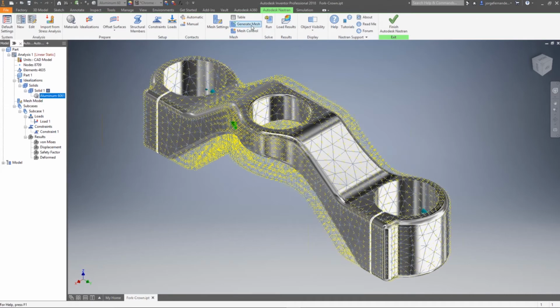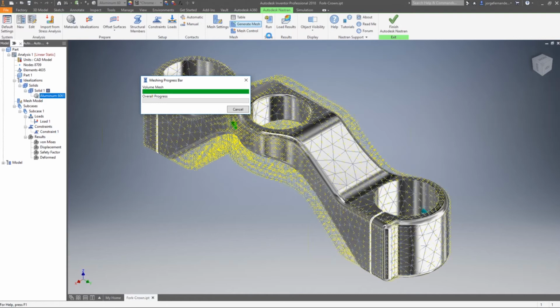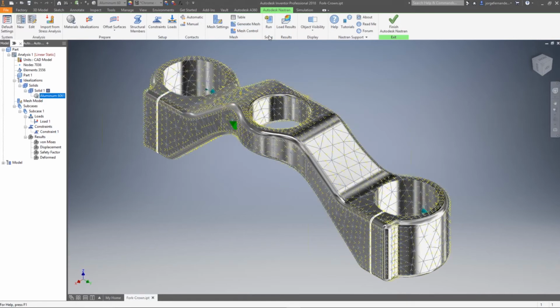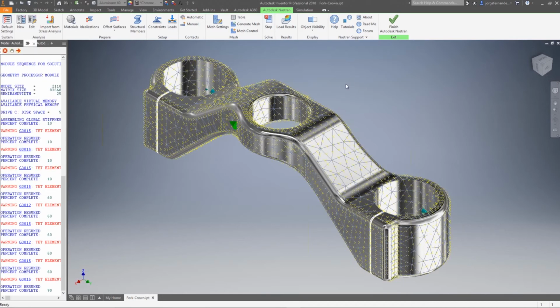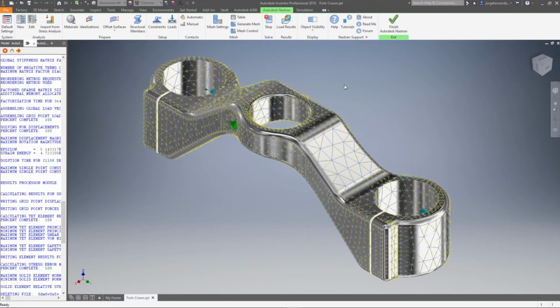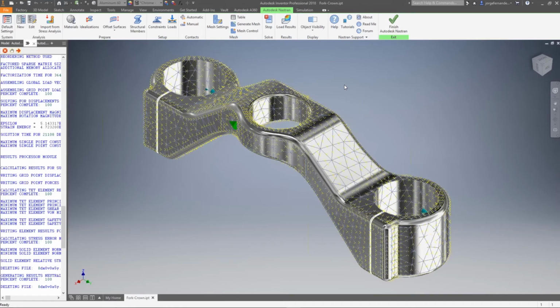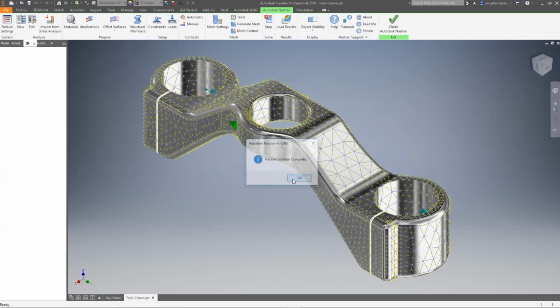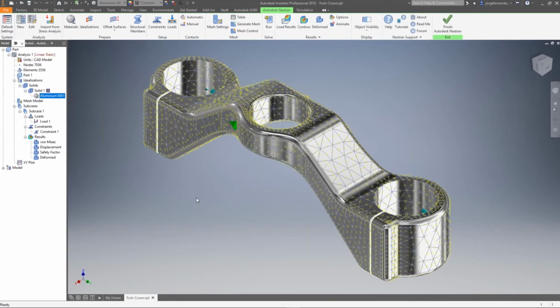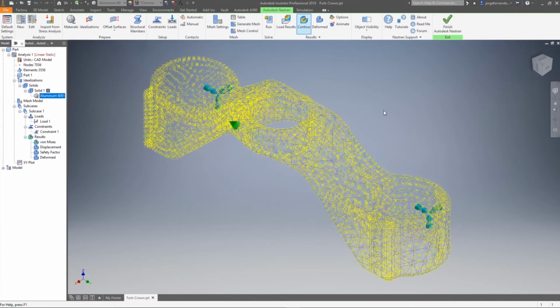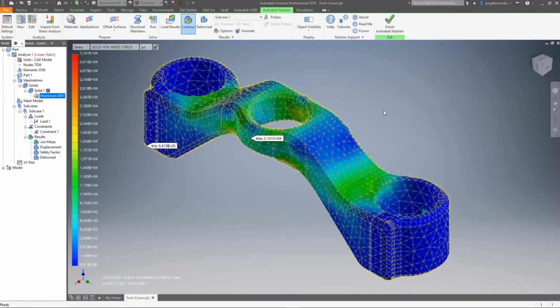All I have to do now is generate the mesh again, assuming, of course, those surfaces are still there, right? Yeah, obviously, if you got rid of those holes and your constraints were to those holes, you might have to do a couple of things. But if it's small geometry changes, it should port straight over. Absolutely. In a few seconds here, I was able to rerun this again, see what the results will be. And hey, is it still within the limits that I'm looking for? It's getting a little closer now.